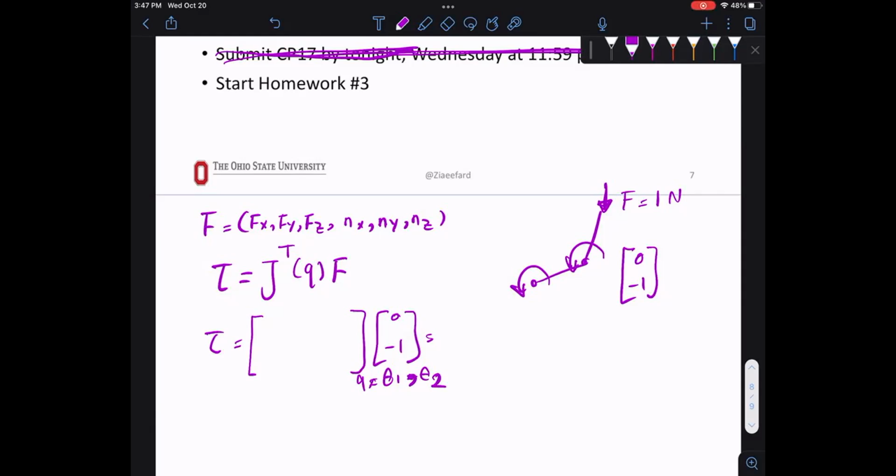So you will find how much torque is applied because of the action that the robot is taking. When you want to spec the motors, you have to calculate those. There will be the torque to move the arm, plus the torque that has to resist, plus some safety factors. That's how you spec.